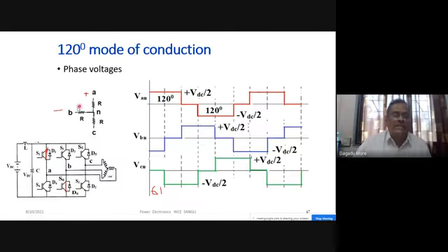And these 3 resistances are equal. So here whatever VAN and VBN is, the total across AB is VDC, the total voltage. Resistances are equal with respect to N, so the voltage will be divided equally, and VAN will be plus VDC by 2. Whereas VBN, with respect to B being negative, is minus VDC by 2.